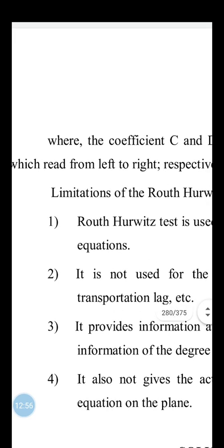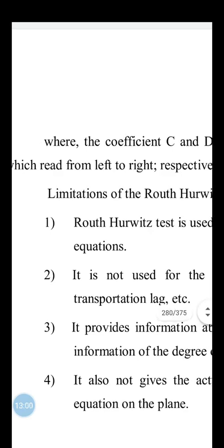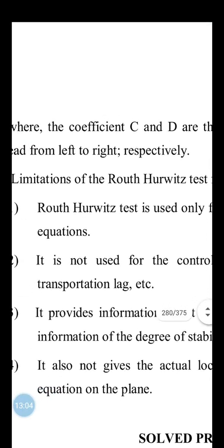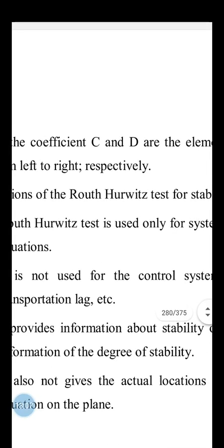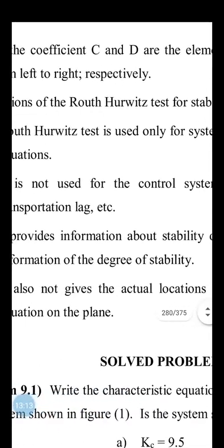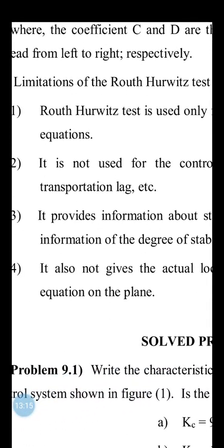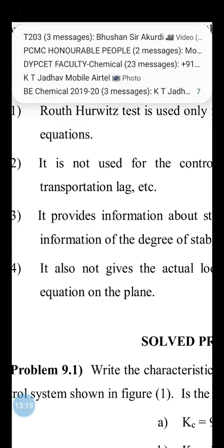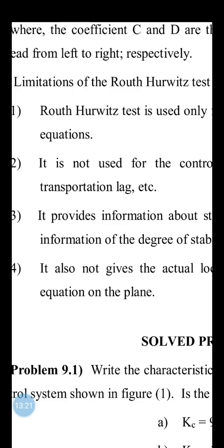There are many limitations of the Routh-Hurwitz test during stability calculations. The Routh-Hurwitz test is only used for polynomial functions. It is not used for exponential functions like transportation lag. What is the equation for transportation lag? It is e raised to minus tau s. So for such equations, the Routh-Hurwitz test is not used.